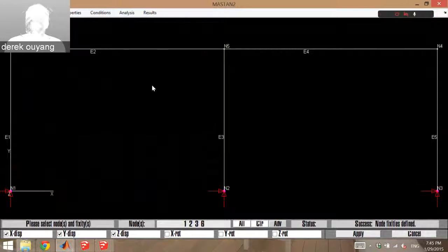So when you have a floor system, you have a slab, and then you have, let's say, two beams below it, 10 feet each, that are holding that slab. It is getting a uniform load, right? But these frame into a girder here. And that girder might be constructed so it's not actually touching the slab. So you actually design this for a concentrated load, right?